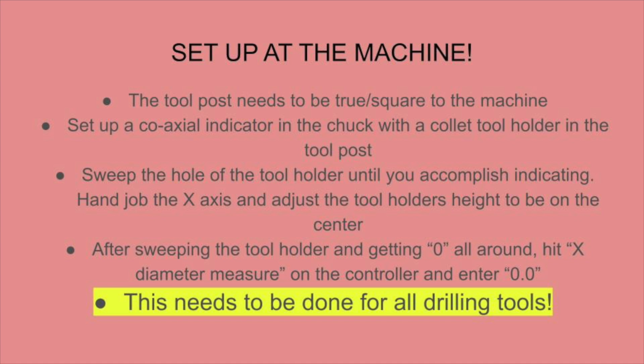We need to be on the center line of the part, and this needs to be done with all drilling tools. This includes spot drilling and drilling.